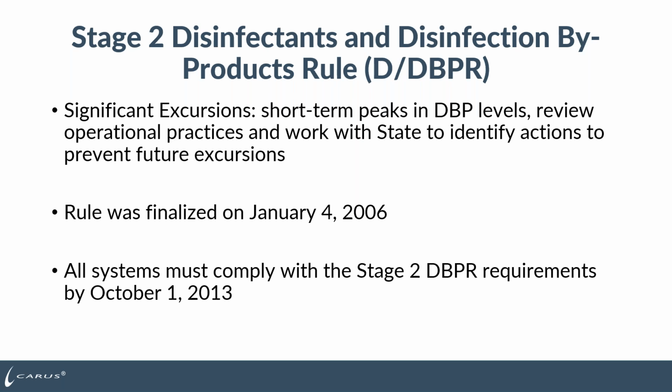In talking to US EPA at the National AWWA show the last several years, the 2 most violated rules typically in drinking water are the disinfection byproduct rule for surface water plants and then the lead and copper rule. So typically when a system has a violation, it's usually one of those 2 things on the drinking water side that causes them to go out of compliance. So that's why it is important to control your disinfectants and the byproducts, because a lot of plants do struggle with this.